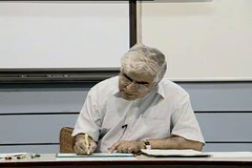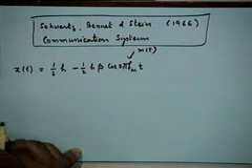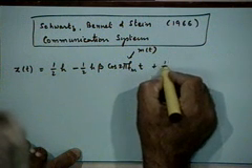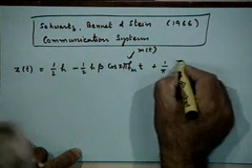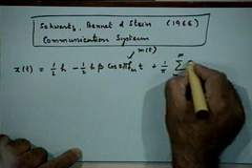It's not exactly a harmonic representation, as you will soon see, and it looks like this: h/2 minus h/2, and there is a parameter beta which I will define shortly, times cosine 2 pi fm t. Here I am assuming that your modulating signal m of t is a pure tone signal, so m of t is cosine 2 pi fm t. So that appears in this expansion, plus 1 by pi sigma m equal to 1 to infinity. There is a large number of terms here.